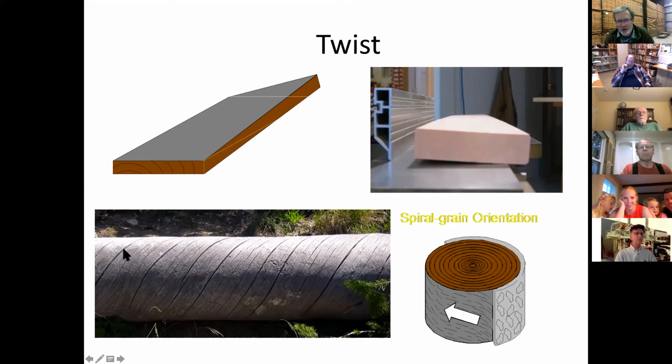So if you saw a board out of that piece and you dry it, what do you think that board's going to do? It's going to twist as it dries to kind of go back, affected by the orientation of the wood cells as it was in the tree. And that's why you see on the joiner here, the twist in this board, there's some angled grain in there.